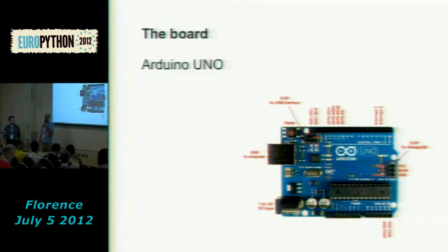We have two microcontrollers on this board. The main one is the big one. You can unplug it and put it in another place, or replace it, and so on. And there is another one, very small, soldered directly onto the board. This is just dedicated to the conversion of signals from the USB to the serial connectors. So it's USB to serial. And then we have a couple of components dedicated to the power supply and voltage regulation, and the quartz here, which gives a 16 megahertz clock signal to the microcontroller.